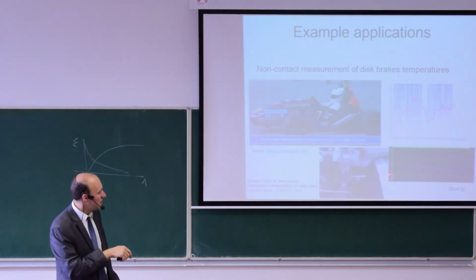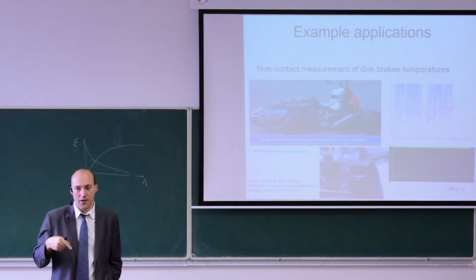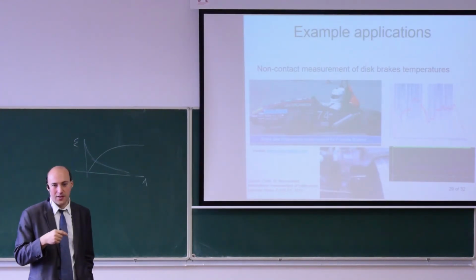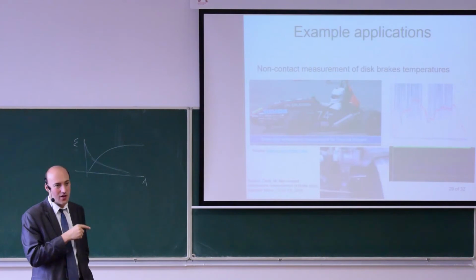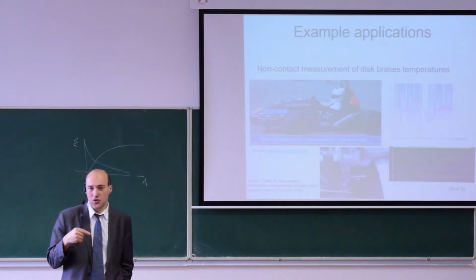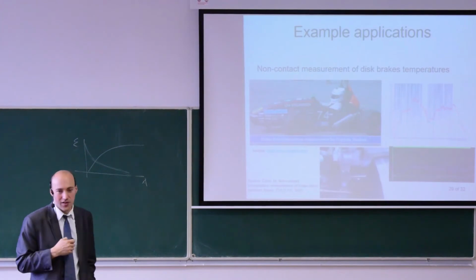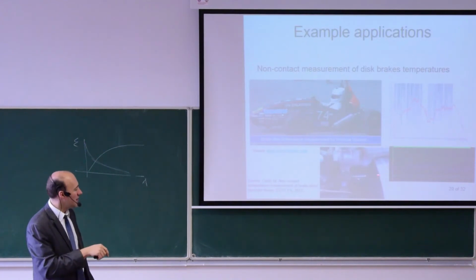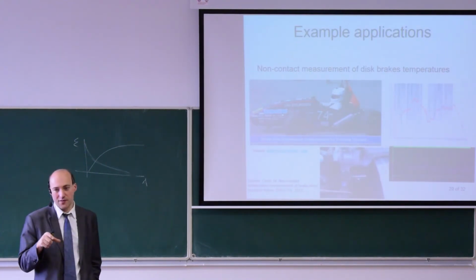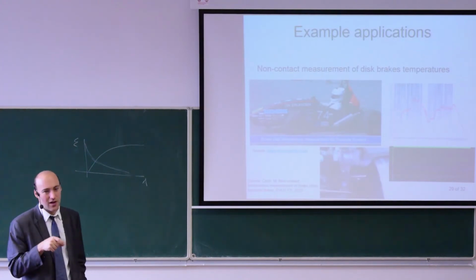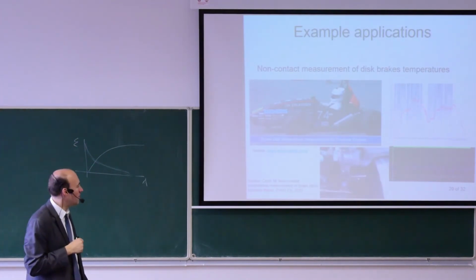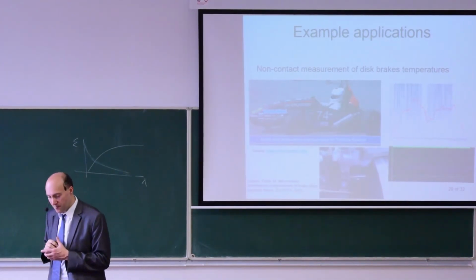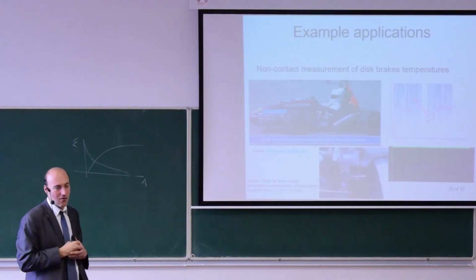But even at those 3 centimeters, when they applied water to cool it down, it created such a huge amount of water vapor that it blocked the infrared radiation. So here it turned out that it's not a good idea to use those IR sensors, at least on those wavelengths, without any extra air, so that we keep the environment clean between the sensor and the disc brake. So this may be an example where even very small distances may cause you trouble in IR reading.